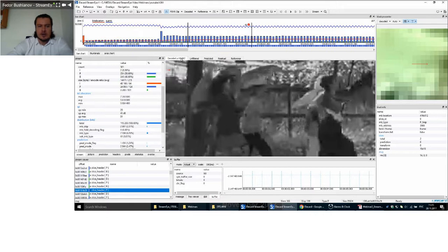So this is the difference. Instead of clicking through tabs and understanding the difference this way, we have another function of StreamEye, which is called difference. So this is the button. In the interface, it's named F. I click on the difference button, and you may notice that in the main window I now have another tab called difference. That's the tab which shows me the difference between selected stages of decoding, or between selected streams, if I'm using a reference stream as I do right now.